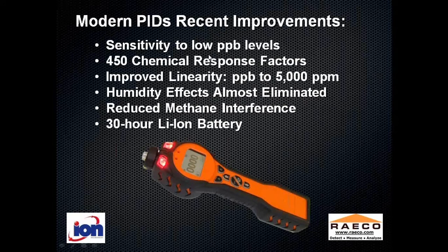This is somewhat repetition. Some of these newer PIDs have all of these response factors built in, so you just dial them up. The linearity has been improved. Humidity effects have been largely eliminated, and there is less interference by methane. And the battery life, there's always improvements in batteries, and so the battery lifetime has gone up to 30 hours in some cases.